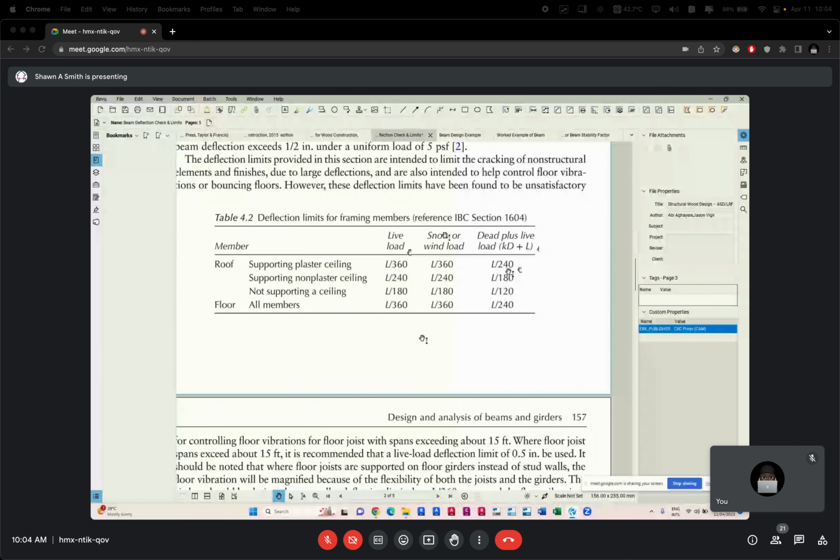All right. What should happen, class, is that for the same element, the deflection should be checked for both live alone and a combination of loads. And it should satisfy both scenarios. It can't satisfy the live load deflection limit and then not satisfy this, and we say it's satisfactory. No, it has to satisfy both, or all three if all three are involved. I said both because we're not going to be looking at the wind and the snow scenario. So we'll be looking at floor live load, or roof live load, and dead load. So it must satisfy the live load criteria and the combined load criteria.